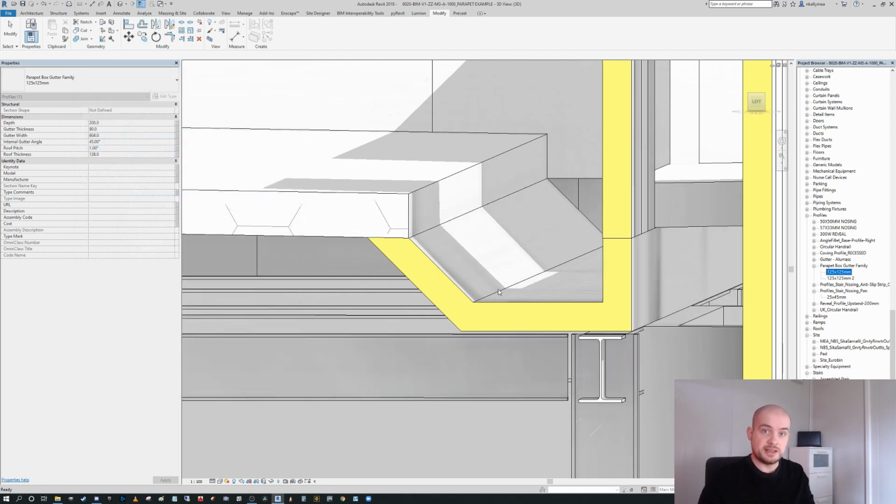And thankfully, as you can see, it's matched the criteria that we needed. It lines with our overall panel thickness. It maintains the panel thickness throughout. It's also falling to the underside of the roof pitch accurately, and we have clearly defined our internal pitch of the gutter fall here. Okay.